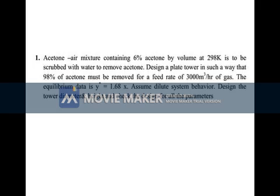The question is: an acetone-air mixture containing 6% of acetone by volume at 298 Kelvin is to be scrubbed with water to remove acetone. Design a plate tower in such a way that 98% of the acetone is removed for a feed rate of 3000 meter cube per hour of gas. The equilibrium data is y star equals 1.68x. Assume dilute system behavior. Design the tower diameter and height and check the design for all parameters.